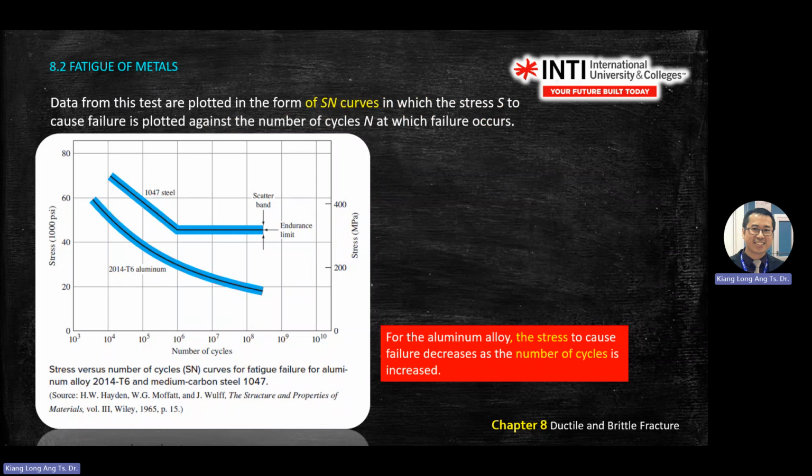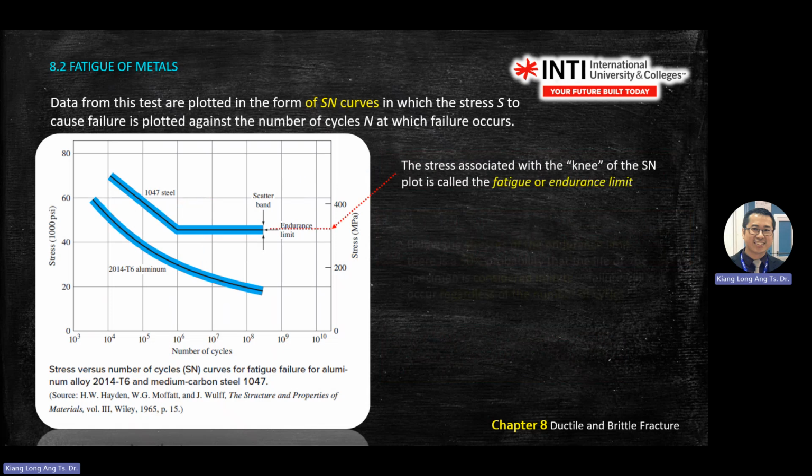For your lab report, you go and find this chart or table from the material encyclopedia, or test it. This one is stress versus number of cycles, in megapascal. Yours is very low, because yours is in Newton. So you take Newton divided by the area of the specimen to get stress, and then you can compare. But this one is only aluminium and steel. You read it.